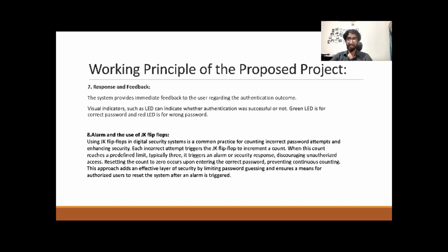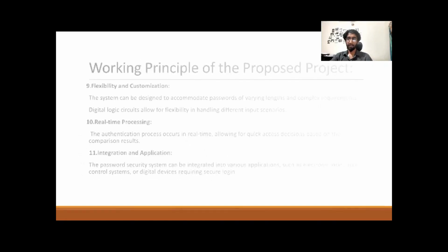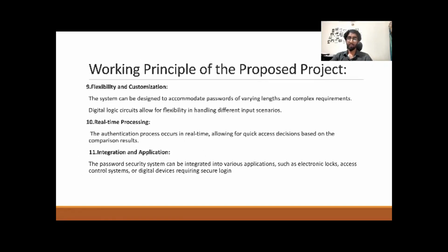Preventing continuous counting, this approach adds an effective layer of security by limiting password guessing and ensures a means for the authorized user to reset the system after an alarm is triggered. Flexibility and customization. The system can be designed to accommodate passwords of varying length or complex requirements. Digital logic circuits allow for flexibility in handling different input scenarios. Real-time processing. The authentication process occurs in real time, allowing a quick access decision based on the comparison result.